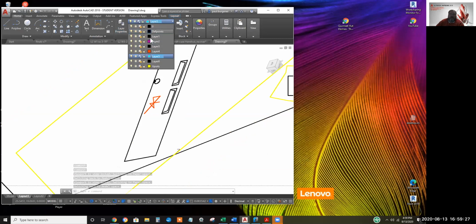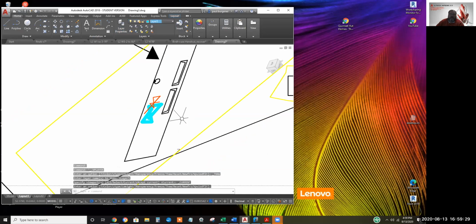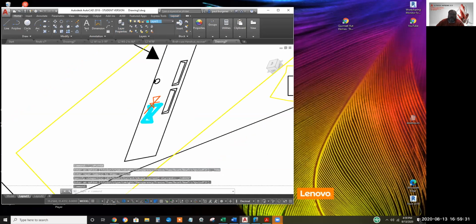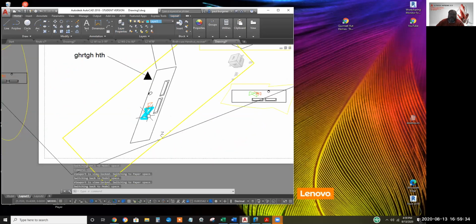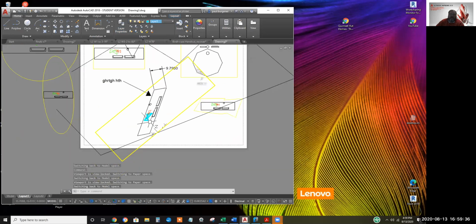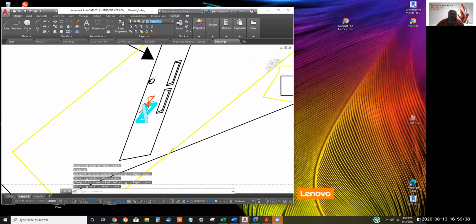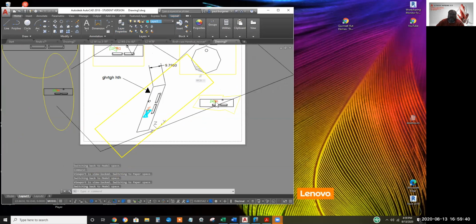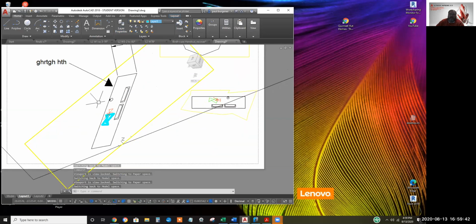That's why it's not showing. There we go. So only in this one viewport, stuff on layer 5 is cyan and fat. And if I had line types loaded, I could make it appear center or phantom or any one of the line types.